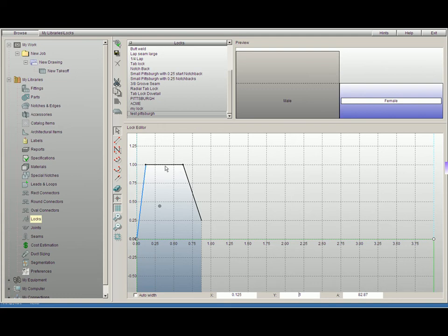Next, what we're going to do is click on this line. We need to make sure that this line is flat across the top. So we have to have a 0 for our y-axis, as you can see here, or our y value. For X, we are going to use auto width because we want this to run all the way across the top. So let's click on auto width. You'll see that PractiCAM is now auto width.